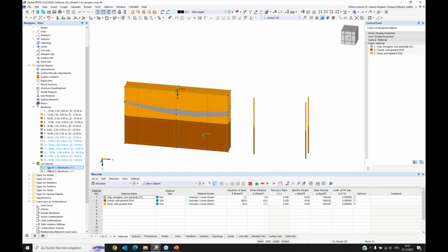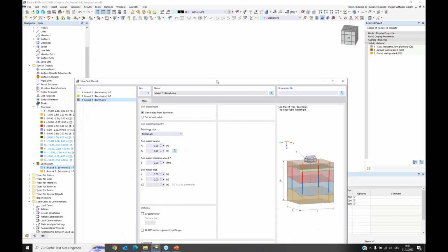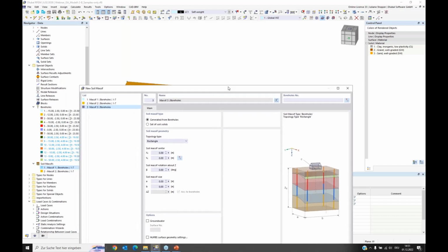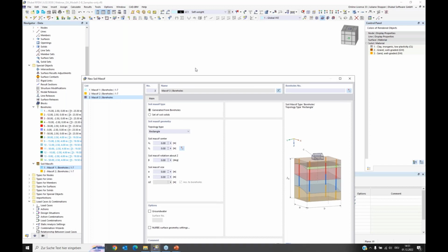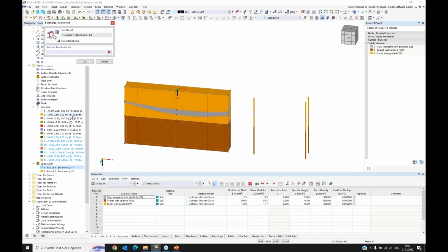Okay, what I can do else is define a new massif, and I want the surface to be in a deeper depth. So I will use a copy. I copy this massif, and it will be placed at 30 next to the previous one, and I will use other boreholes. For this case, I prepared a copy of these boreholes, and in that copy I set another Z value, and the height is different. So you will see the effect soon.